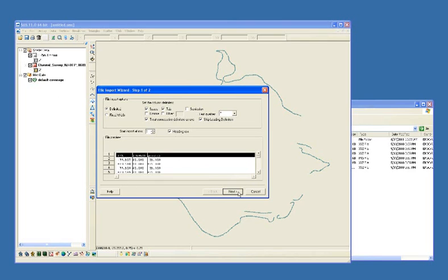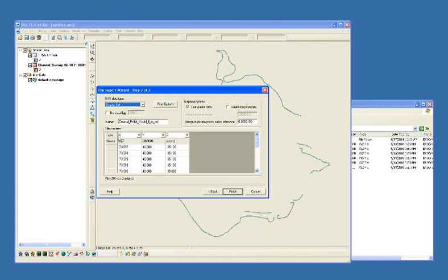There's a certain number of points. Now we're not going to make any kind of horizontal projection changes or anything. We're just bringing in the data. We have to know where that data is and what the projections presently are, and we'll change that later on. So you notice that these are -73. This is coming in geographic coordinates. So we'll click Next, XYZ, Finish.